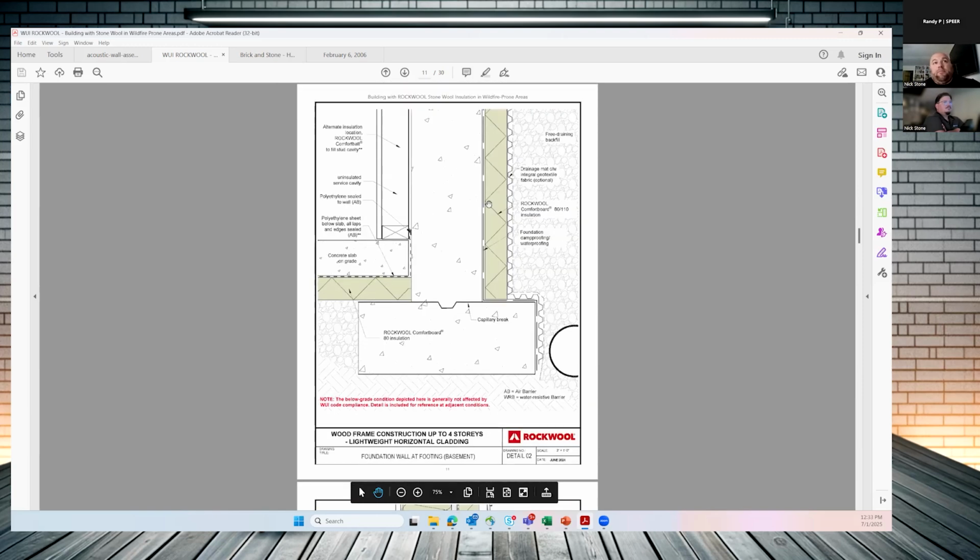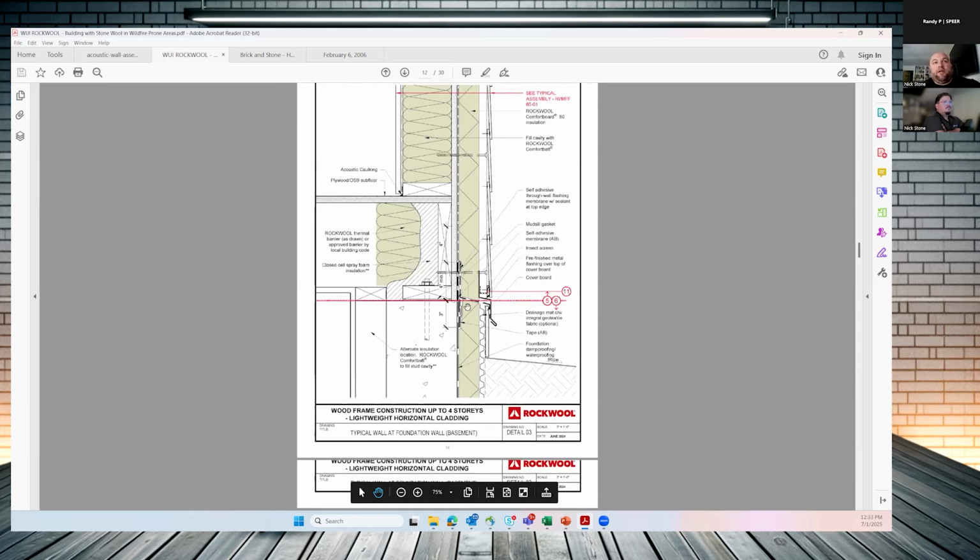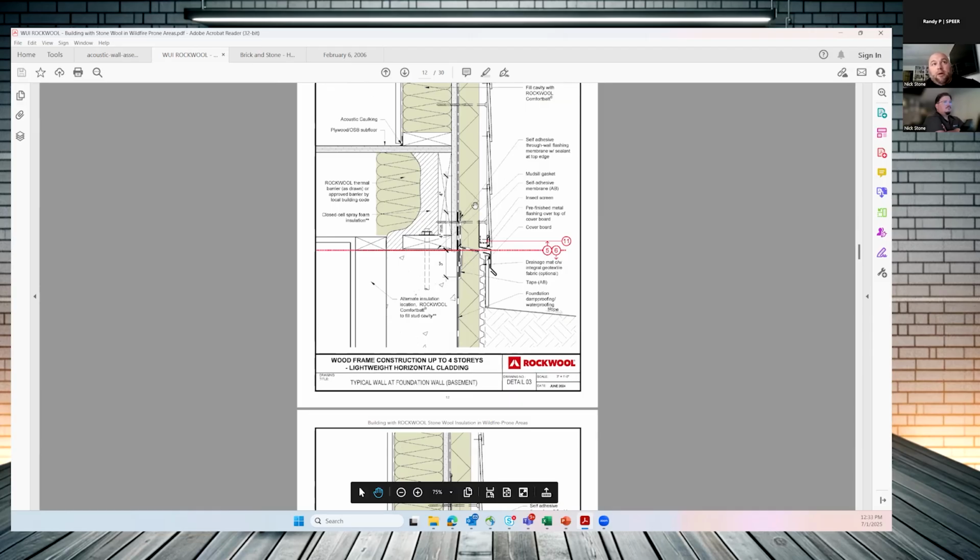If you're doing a little below grade work up against that stem wall, you can actually bring that insulation below grade, just like you see here. You can stucco over this portion, so it can be just as normal as your neighbor's house or the houses down the road. So it has that kind of stucco style finish down there.